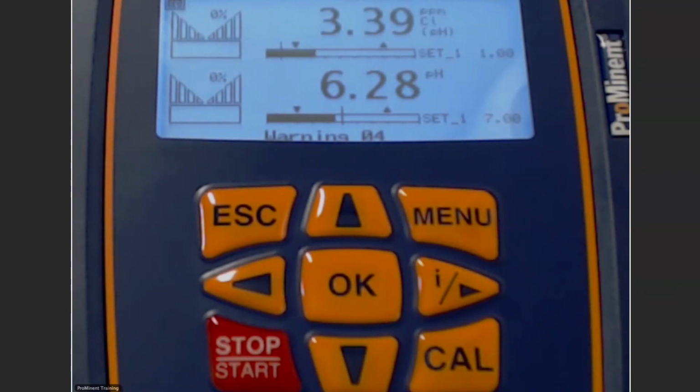And that was the same way we did that on the D1CA, and the D1CB has to be done that way as well. Remember, the D1CB is still available for us. It doesn't have pH correction, but if we're using that to decrease any of those values, if we're controlling to decrease, we need to set that control output to minus 100. Okay, that's a very good question. If that's not clear, if you still have a question on that, follow up with me. I'd be happy to help through that. But hopefully that explains it for you.